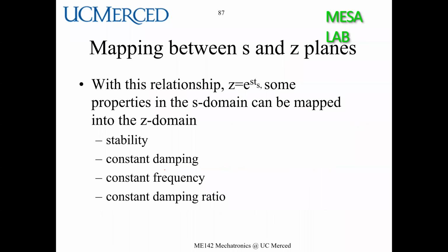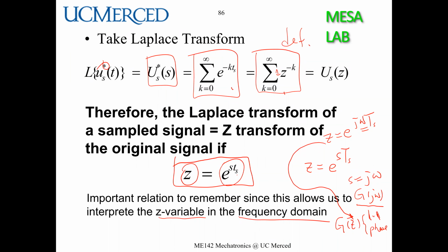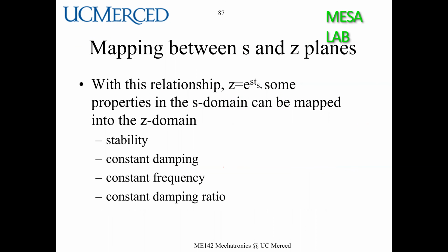But in reality, you can see that this is not algebraic, not polynomial. It's a transcendental function, exponential or logarithm. It's difficult. So then we are going to check G(s), can we tell its stability? If you have a polynomial, you can use a Routh-Hurwitz table. You can use Bode plot, gain and phase margin.